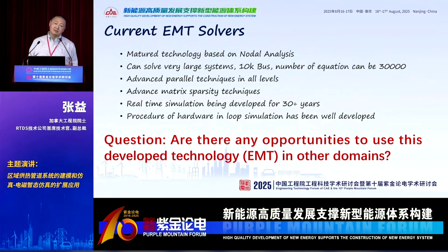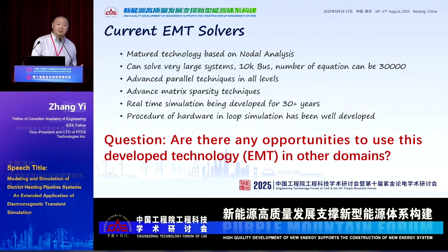In the recent 30 years, we developed real-time simulation, with which we can run the simulation tools in real time and then do hardware-in-the-loop testing using the digital simulation. This is one of the advantages. We can test the equipment without connecting it to the real power network. So the procedure of hardware-in-the-loop simulation today is very well developed.